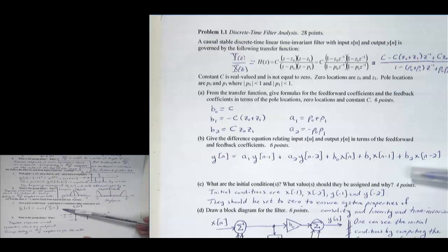So this is lab 2. Cosine generation. If you look at the three coefficient case, my averaging filter is 1, 1, 1. This filter, the signal is 1, 0, minus 1. So the product just becomes 1, 0, minus 1. Again, we have odd symmetry in the impulse response about the midpoint, and we have generalized linear phase.